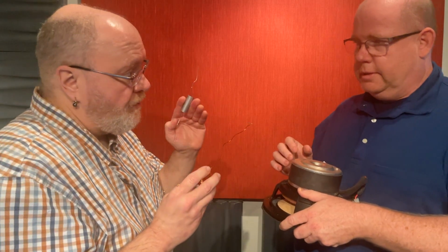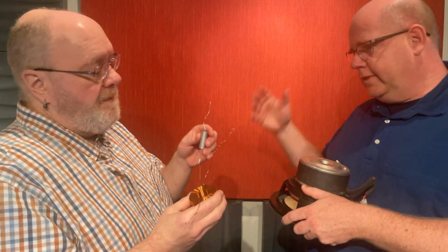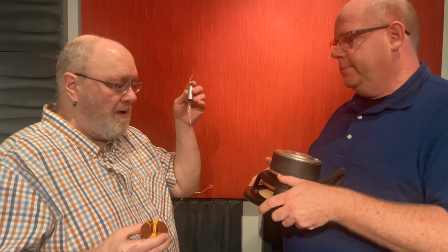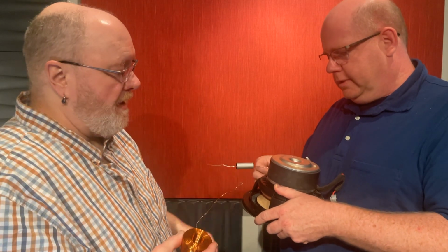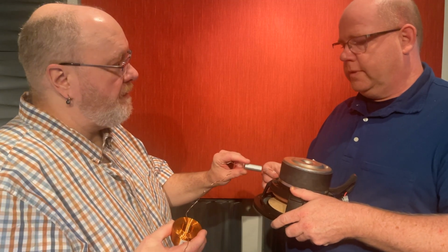On a 12 dB per octave filter, if you want to go more aggressive with filtration, you want to get that 500 hertz and above. There's a combo to just drop fast. It's the combo. So I take this one, the same thing, in series. This is going to filter lows at 6 dB per octave.